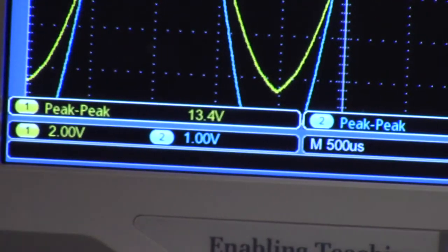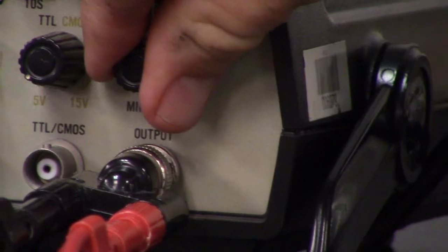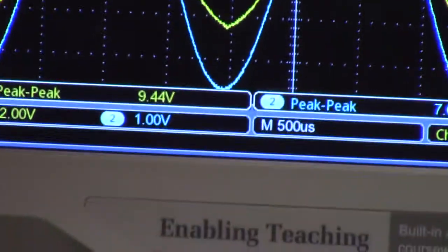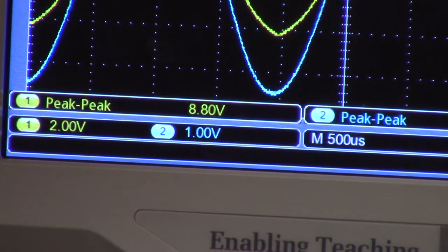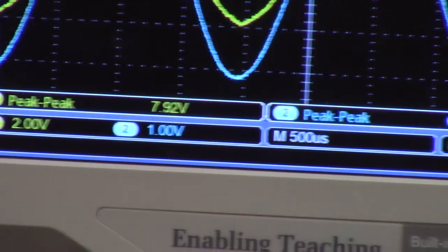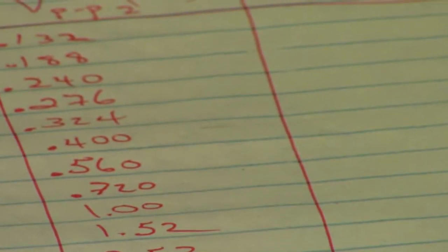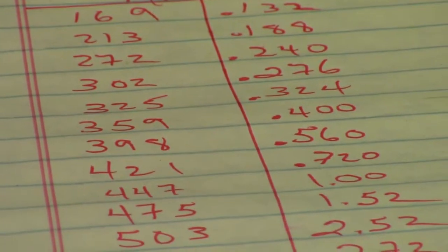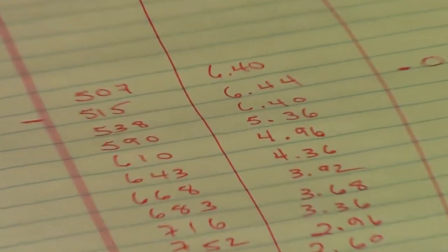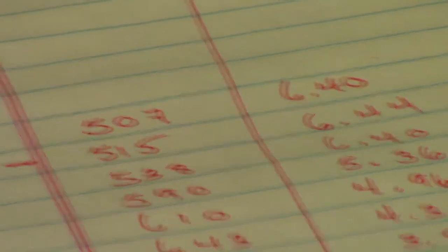And again, we want to make sure our voltage is at 8. I had turned it way up while I was adjusting it just to make sure it would stay high. All right, and so there's an 8 and 6.4. So 6.40. Yep, just a little bit of drop. Actually, the same drop the other direction there. Okay, and maybe I'll tighten it up. But you can see they're in phase again. We're back to resonance. Okay, so I will go ahead and make a small adjustment.